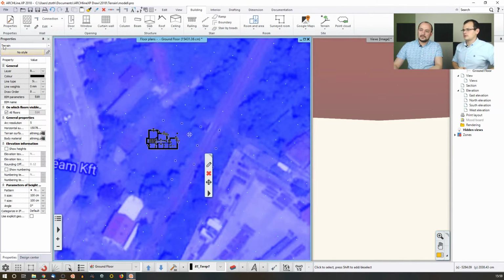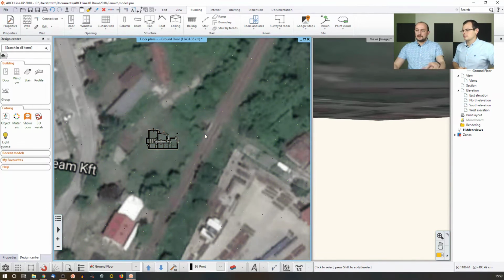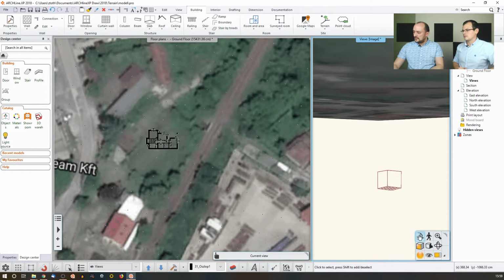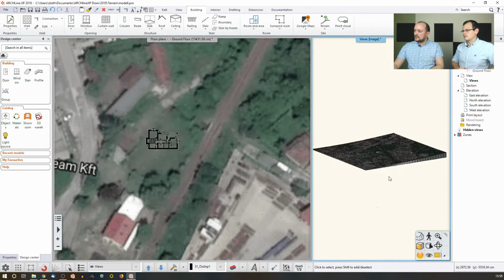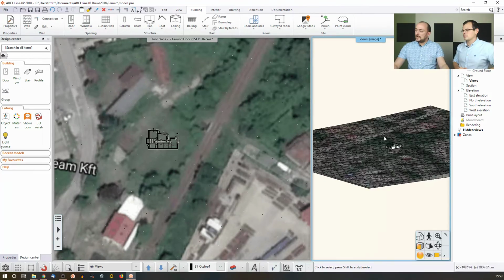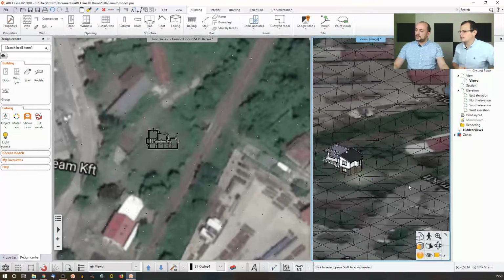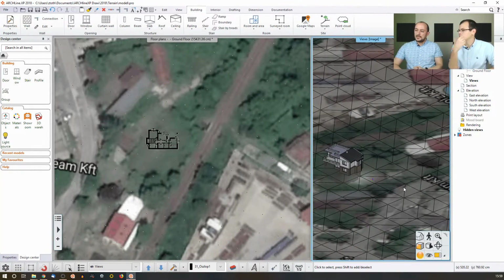This is a terrain with a specific satellite view, and there's this view here. Now I go to the axonometric view, and see now I don't have any problem with the building snapping to the ground. So it's automatically snapped there? Yes, when you import something from Google Maps, the software automatically reads this origin level, and then it auto snaps the building together with the terrain, so you don't have to worry about that. If you would like to, you can change it the same way.